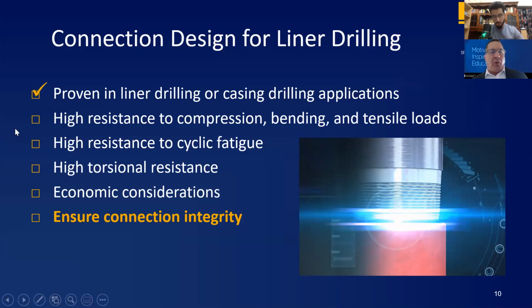So you want your connection to be proven in liner drilling or casing drilling applications, or make sure it's been run successfully before in the application you're looking at. You want it to have high resistance to compressive, bending, and tensile loads. A lot of mechanical forces, the same forces you would see when you're drilling a conventional assembly as you would in liner drilling. And the most important right here is high resistance to cyclic stress fatigue.